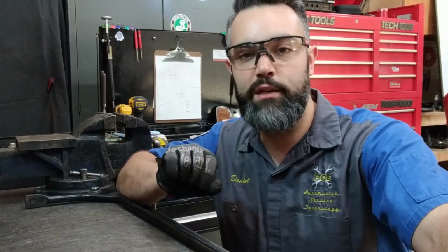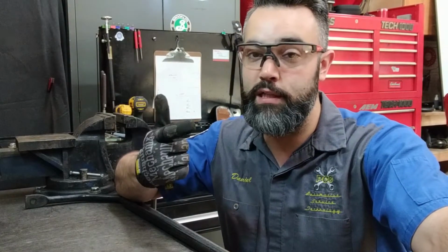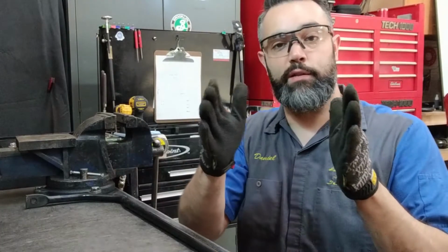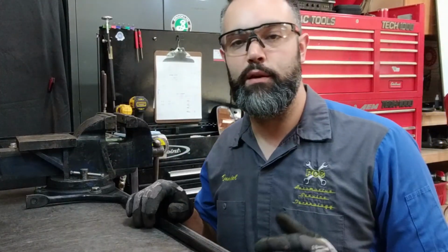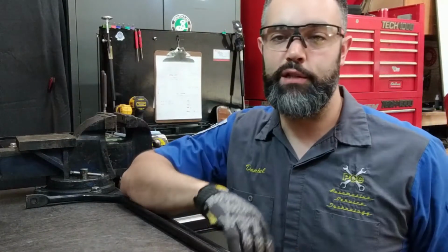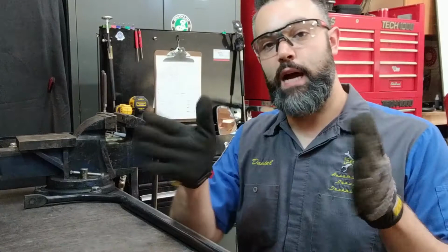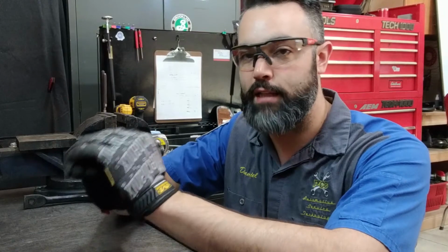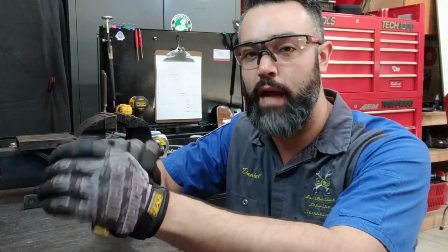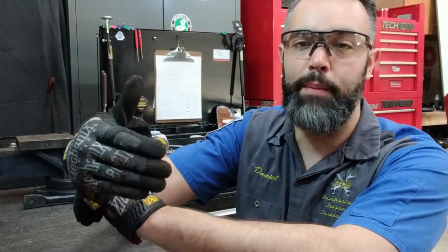Depending on what changes are made, sway bar stiffness may affect things like understeer and oversteer. Understeer is where the front tires will turn, but the vehicle continues to push against those tires and not follow the direction that they're turned. And oversteer, which is what drifting is all about, is where the tires are turned and the rear tires lose traction. Sway bars have a lot to do with the handling characteristics of the vehicle and how it's going to react from the front to the rear. Typically, a soft front sway bar and a stiff rear sway bar will promote oversteer.